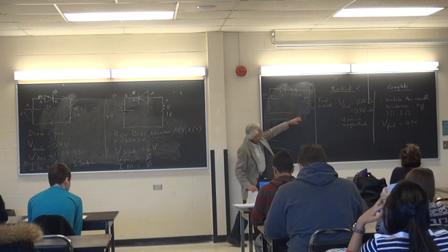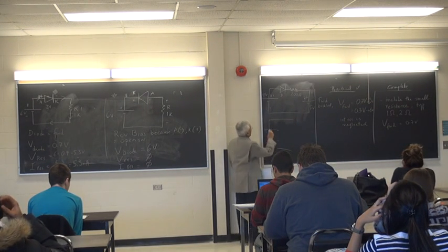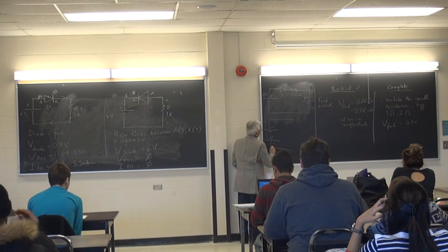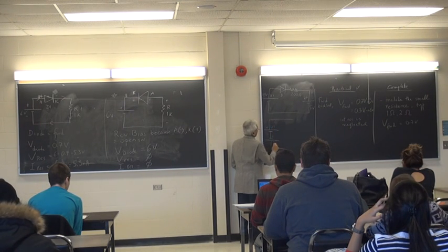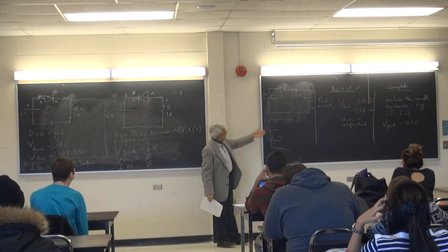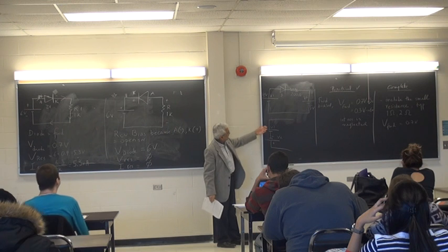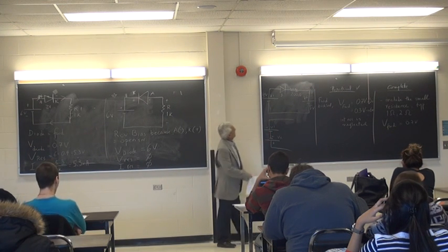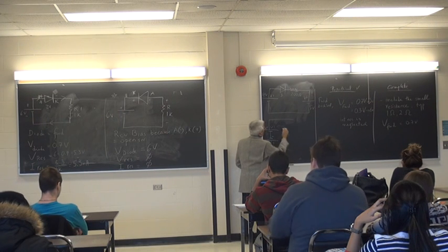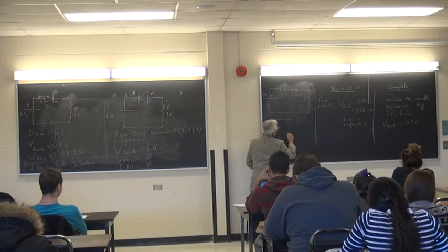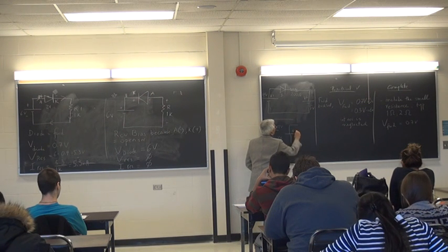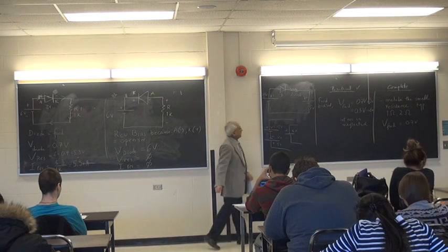If I move V2 over right beside V1, then it would be minus at the top, plus, and then plus and minus. So what happens is the voltages add up or cancel out. They will cancel. So I've got 9 volts, I've got 5 volts. It'll therefore become one equivalent voltage of 9 minus 5, which is 4 volts, with the plus at the top.